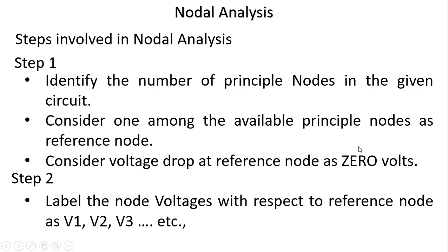Coming to the steps involved in the nodal analysis technique. First, you have to identify the number of principal nodes in the given circuit. Consider one among the available principal nodes as the reference node. Consider the voltage drop at the reference node as 0 volts. So these three we are aware of. All this is step number 1.